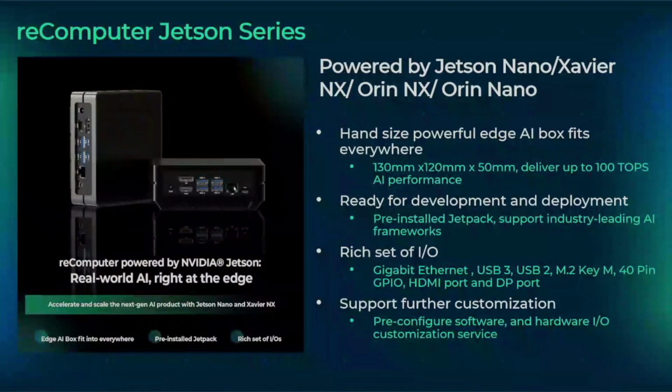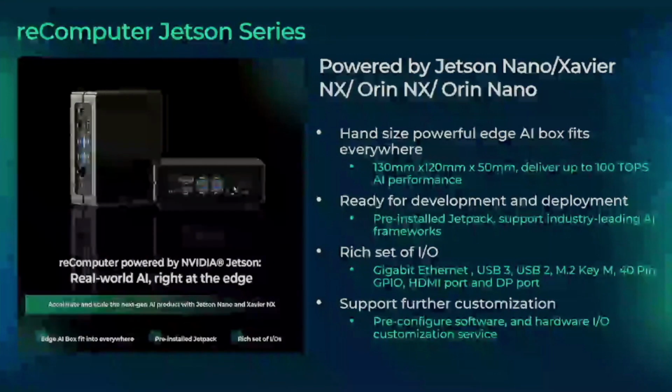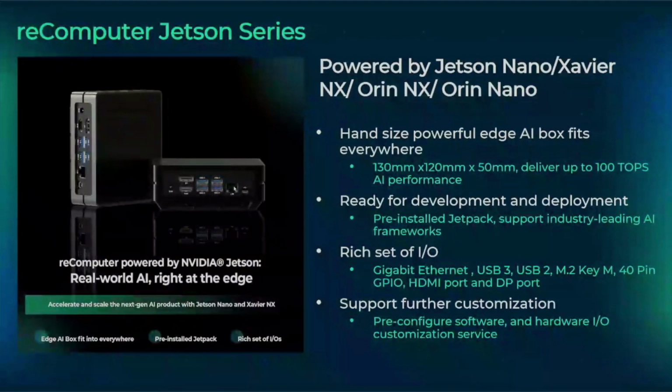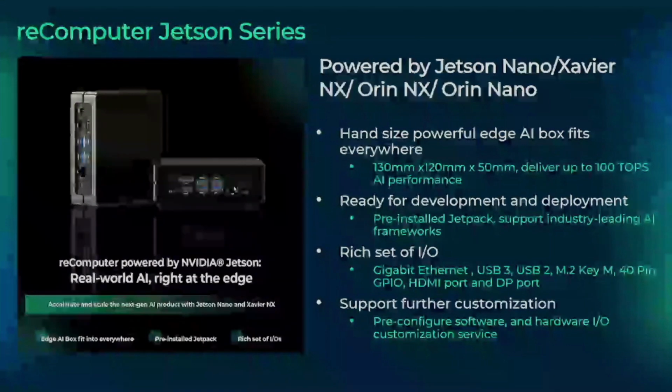On the developer kit released by NVIDIA, those are powered by micro SD cards. When you use micro SD cards, as you all know, there's a limit to how much you can read and write until the card gets damaged or dies. So you cannot have a reliable operation with the SD card. That's why we go for this kind of solution.